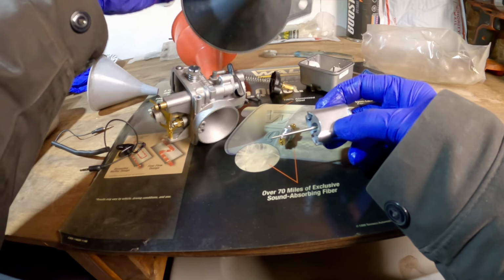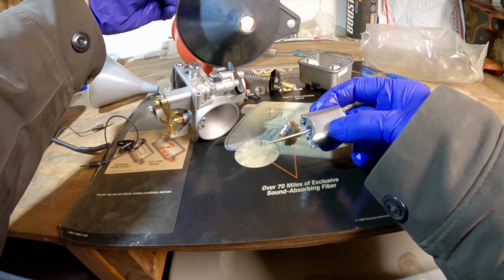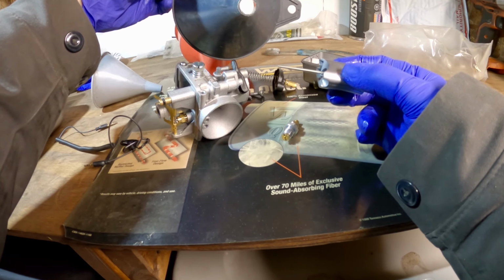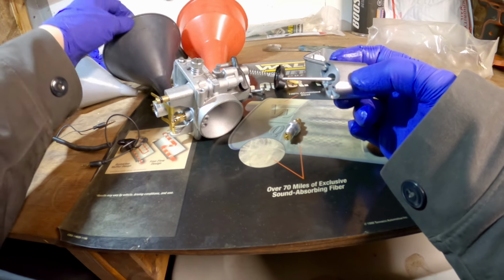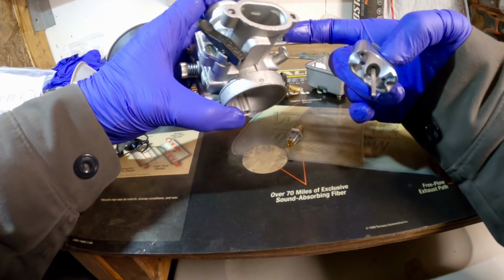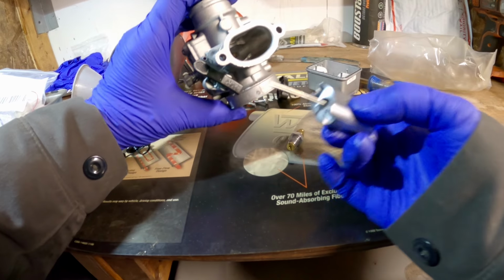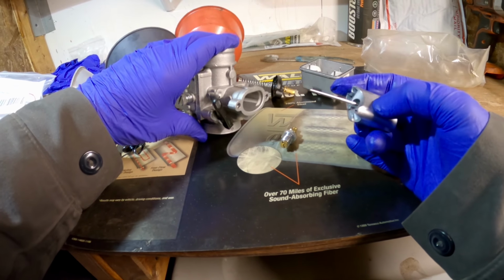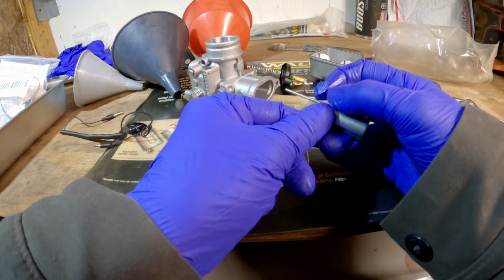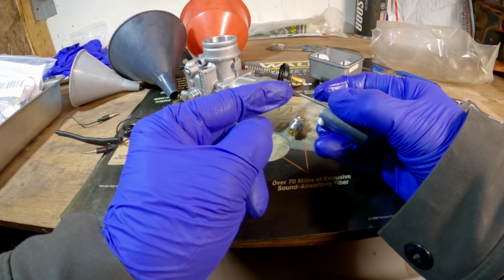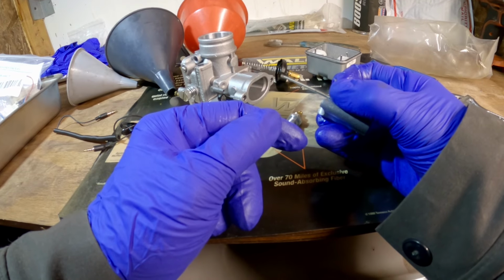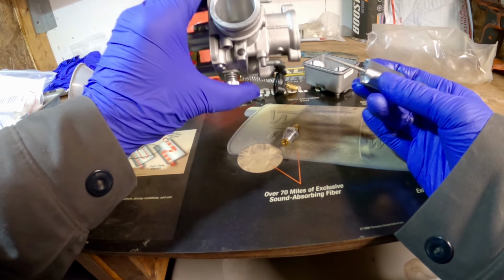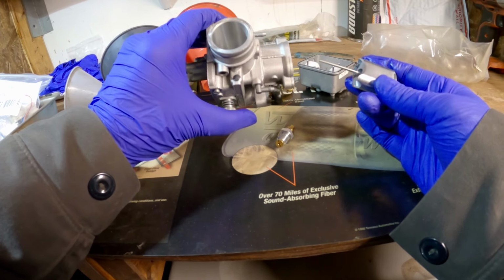So remember the example with the funnel, and I stuck that punch through it. This has a taper and that punch had a taper. Okay? So now imagine this is this orifice, this brass orifice that this needle is going into. As you pull this out, like I was saying, if you take a slice here on the taper, that diameter is going to be bigger than the slice here on the taper, therefore increasing the cross-sectional area, the flow area for fuel to come through.